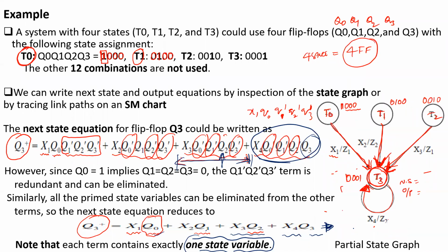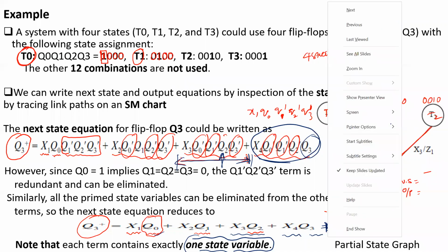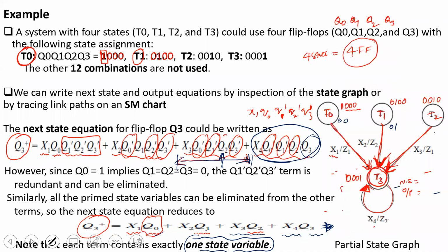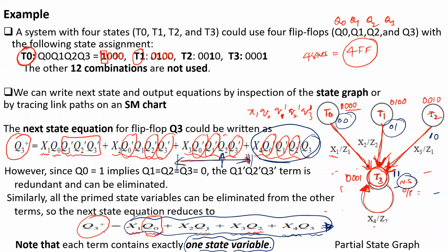Okay, for example, if you consider this one is 00 and this is 01 and this is 10, this is 11. If you are using this one and you find the next state equation, you'll find a huge equation there. When compared to the next state equation according to this particular scenario, the hardware cost is very less. Very little hardware is implemented when compared to this one.